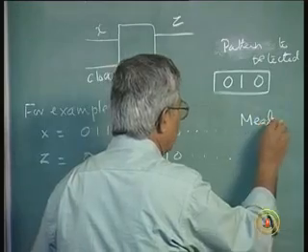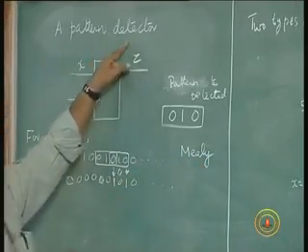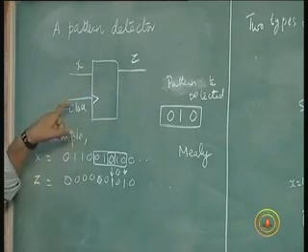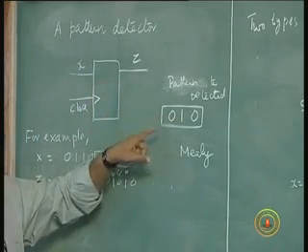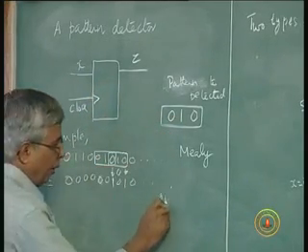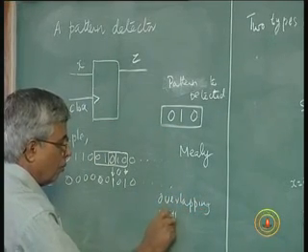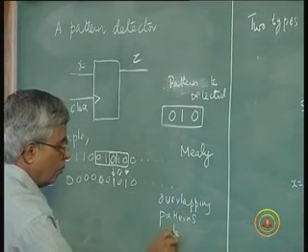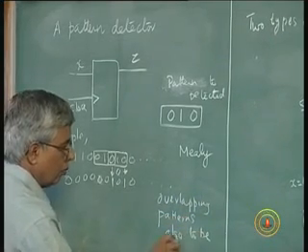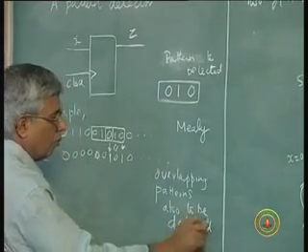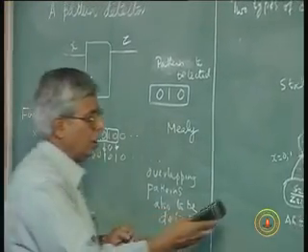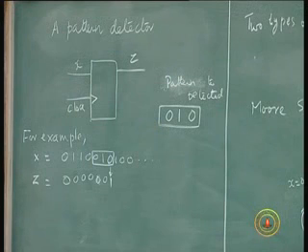So these are my input specifications. This is the pattern detector, one input and one output with a clock. Pattern to be detected is this, and I want it as a Mealy machine, and I want overlapping patterns also to be detected. With this I go to the next step of the state graph drawing. I may not draw the best state graph, but I should start somewhere now. I have to get going.